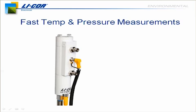That's another great question. We're actually looking into this. The 7200 is capable of fast output of mixing ratios, and they can be corrected for dilution and expansion using the instantaneous water, temperature, and pressure measurements. So this can eliminate the need for applying the WPL terms.